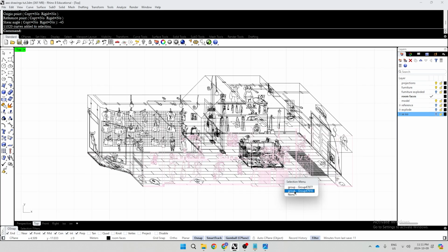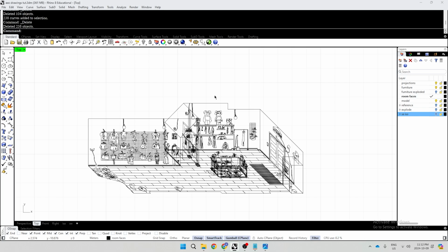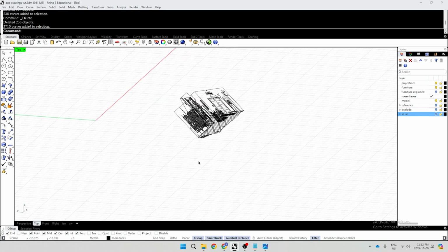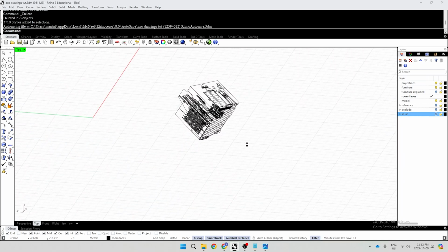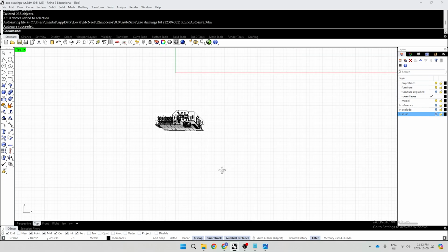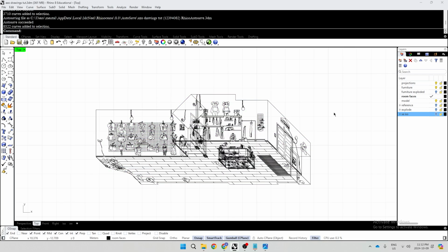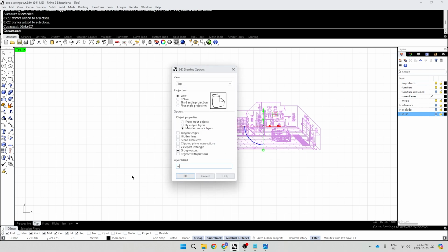And I just want to delete the walls I don't want to see, like last time. This one. Okay, this is how you make an elevation oblique. If you zoom out of your viewport, you can see this is very weird. Because Rhino is a projection of 3D model space, this is kind of like a cheat way to make projection drawings. And like last time, make 2D, name it.